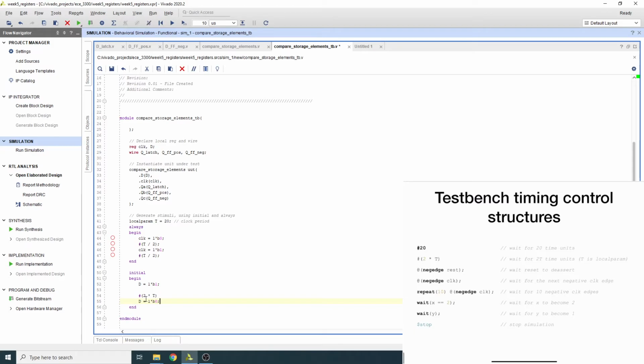These timing constructs are visible right in front of you here. The first one is the one we saw, and this one is the one that I just included. Let me show you this particular one. Because I have a clock now, I can use the positive edge and negative edge. So I can say, wait for the positive edge of the clock. Here I'm going to say wait and then do nothing, so I'm going to use the semicolon. If you don't use it, it will not work as expected.